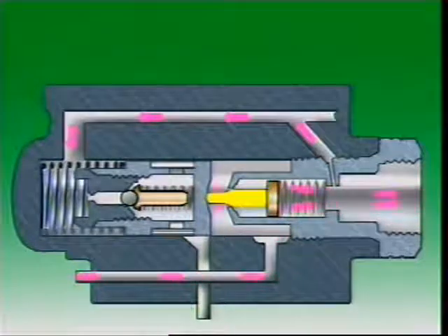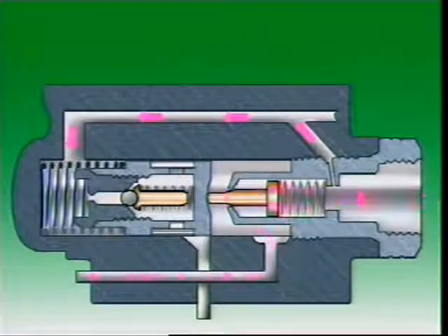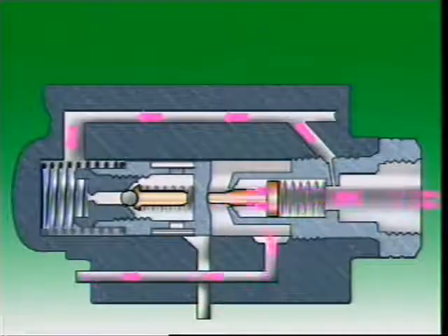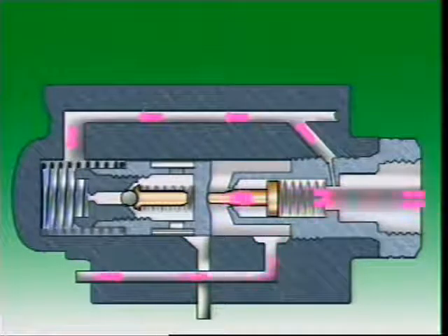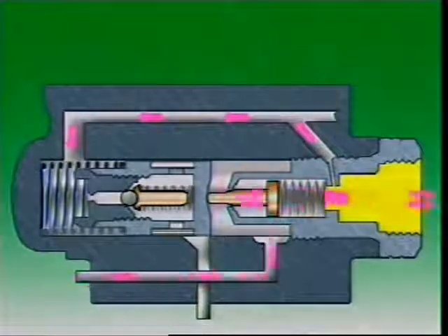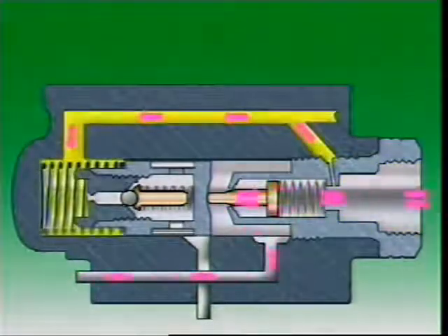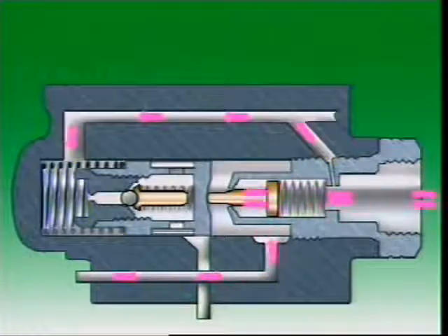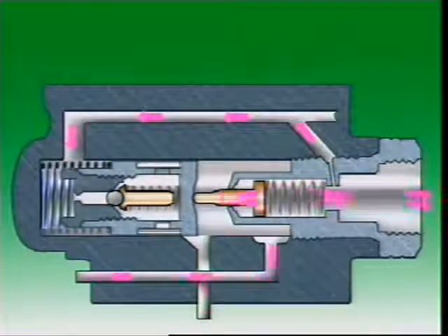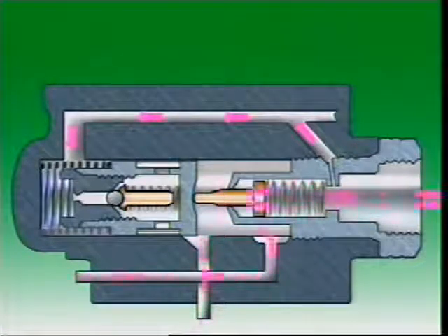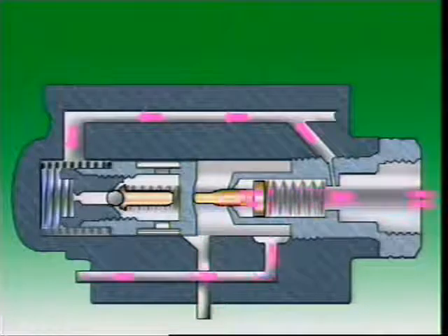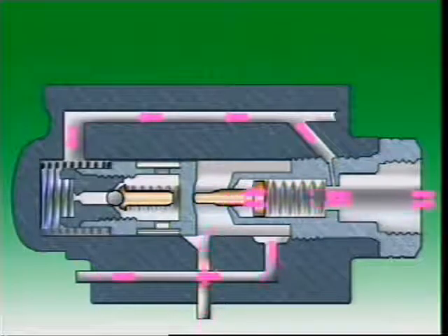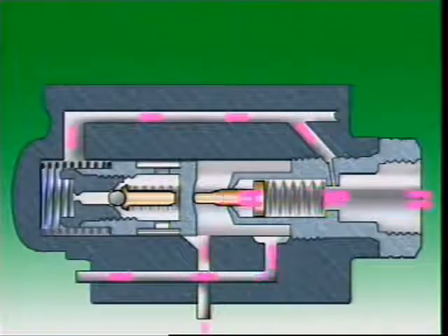Movement of the control valve controls the position of the needle valve in the outlet fitting, and this controls the fluid flow to the steering gear. At higher speeds, with no steering maneuvers, fluid flow is increased. This reduces pressure at the outlet. The lower pressure is transmitted to the spring end of the control valve. The valve moves and opens the return port back to the pump inlet. Movement of the control valve also controls the movement of the flow control needle in the outlet fitting. The needle closes in the orifice and fluid flow to the steering gear reduces.